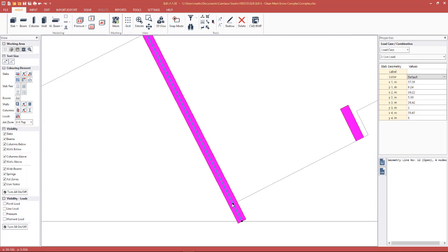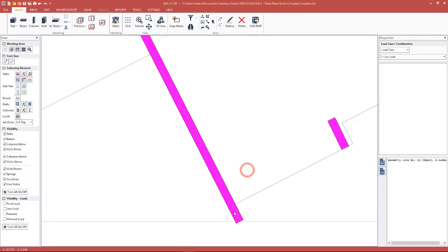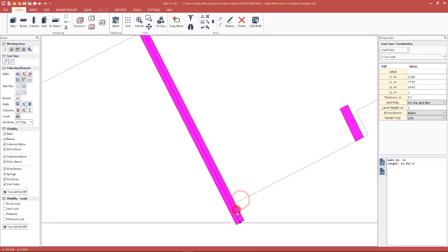So we want to get rid of this node. Here is one example where the automated tool of adding a geometry line node at geometry line intersect had some undesirable consequences. When it was added, it was probably the exact location with a high degree of accuracy. However, when we round it off, it is now in an incorrect location, hence why we have many, many closed node meshing errors along this wall length. So to tidy it up, we will get rid of one of the nodes. So right click, remove node.